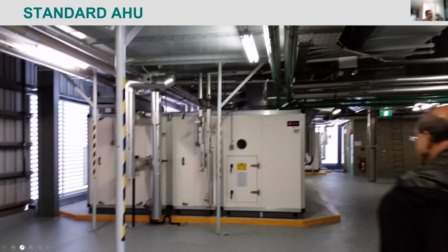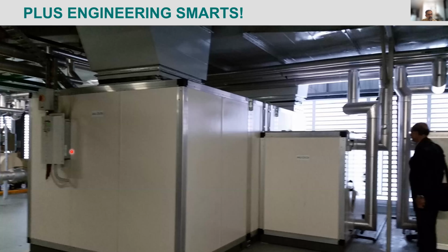But if you look on the other side of the same air handling unit, this is the magic box. Okay, this is a box that takes outside air from the open louver grills. It has its own chilled water connection. So this is where you get the coldest water hitting the hottest air and getting a really efficient heat exchange over there. So once that was all done, it was constructed, commissioned, we watched the meters, we collected the data,